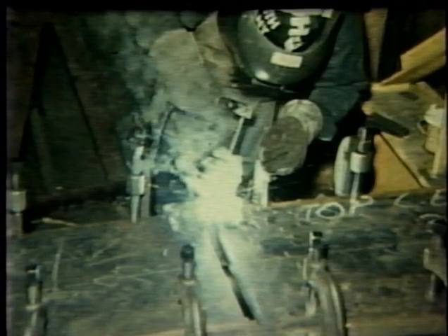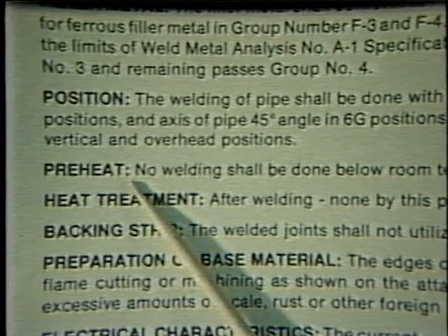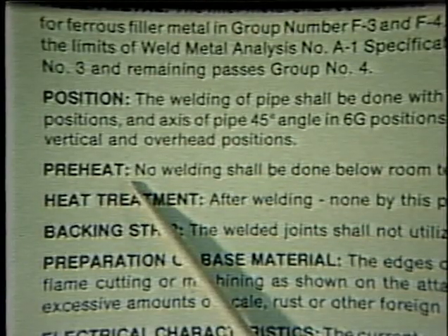Welds that are too small for the plate thickness or excessive joint restraint caused by improper clamping or fixturing can promote hot cracks due to contraction forces during solidification. If this occurs, check the weld procedure for proper bead sequence or for recommended preheating procedures. These factors tend to reduce contraction forces.